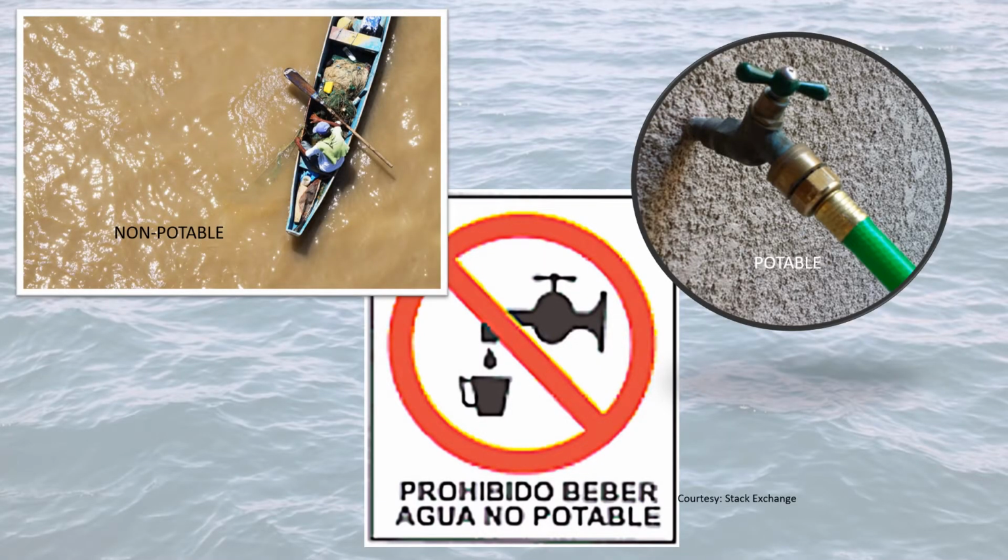Water. Water to make stucco should be potable. This means fit to drink. Potable water will be free of harmful chemicals, salts, or other impurities that can affect stucco.